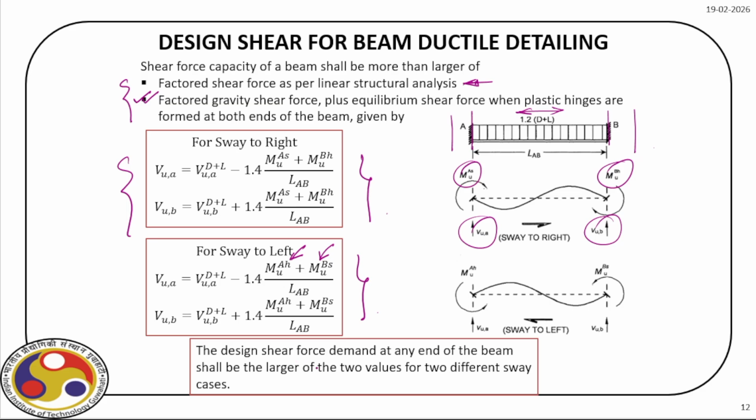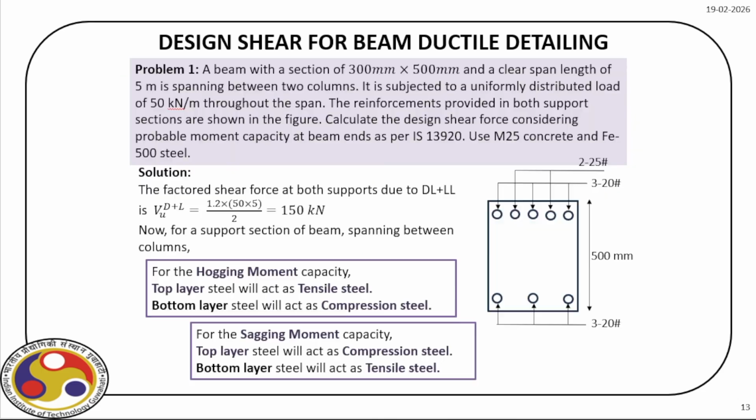The design shear force demand at any end of the beam shall be the larger of the two values for two different sway cases. So we have two different sway cases here, and then we also have the linear analysis. The larger of these values we should consider when we design the reinforcement against shear. Now, for that, let us consider a problem.